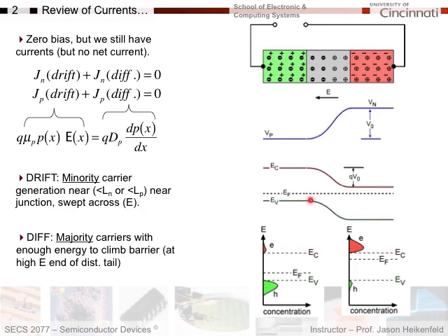And so again, what we care about is minority carrier generation. Minority meaning there are few electrons compared to the majority, which is holes. Within the diffusion length of the edge of the depletion region, it experiences the electric field and gets swept across. We have the same thing for holes over here. An electron thermally generated is the same as thermally generating a hole. If it's within a diffusion length of the edge of the depletion region, it can be drifted across as well. This current is also very small because up here on the P side, we don't have that many electrons. You doped it P-type, and all these excess holes kill off and reduce the electron population. Same thing for the holes on this side. This is N-type material, and so all those extra electrons kill off most of the holes by recombination, so you don't have many holes that can go back across here.